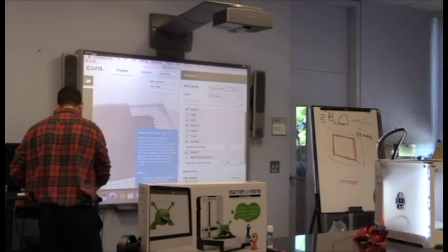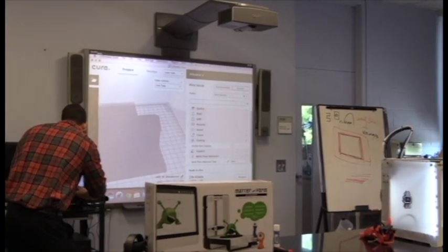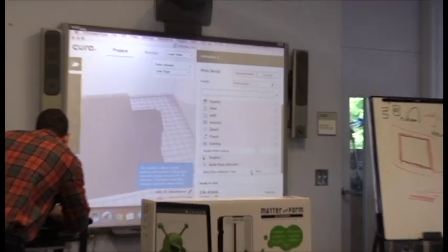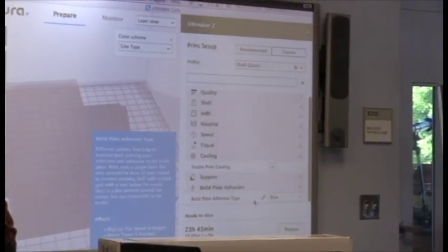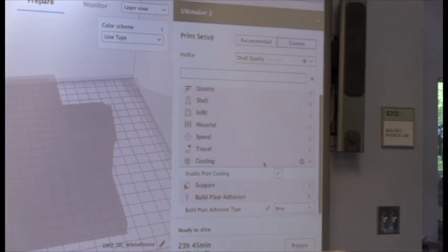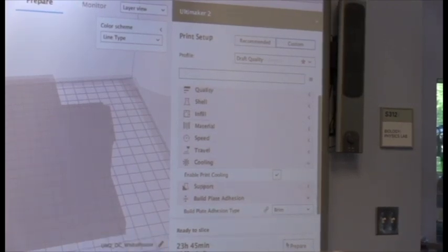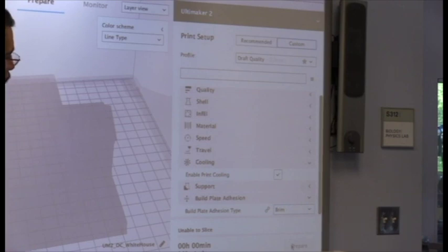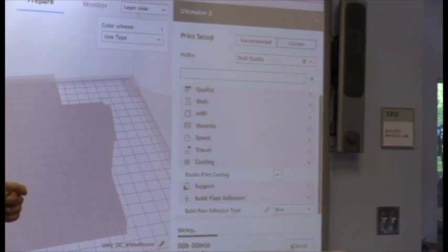Let me show you. Let me demo this thing. So let's say I have a brim over here. Add selected brim. Usually it lets me know how thick I want it. I guess in the new software they took it out. Let's see what this looks like. Prepare. So usually you can define how thick you want it. I'm sure they moved it to the back. So in the back you can handle, okay, when you click brim you want it to be 0.8 millimeters, 0.5 millimeters. You don't want a lot, usually you want a few more layers. If it's like a standard thing, like just a straight up cube, you don't want anything, you know it's going to be nothing. But if you're doing what you were talking about, then yes, you want more adhesion. Add a brim.